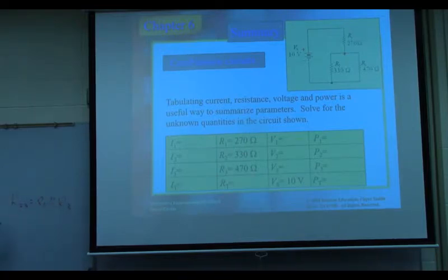Okay. I like you to write as neat as this. R23 means R2 parallel R3, or sometimes you can put a comma here, that's fine. R2, R3. So that one will equal R2 times R3 over R2 plus R3. Yes. So that is the combination of the bottom two. And what is the total? The total will be this one plus the first one, right?